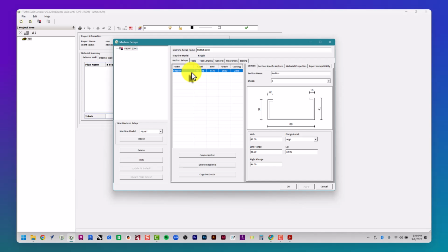And I definitely can't have walls on the exterior that are rated for non-load bearing, right? Because those exterior walls typically are bearing load. So I can have multiple sections. What I'm going to start doing is I'm going to set each one up, starting with the section name.